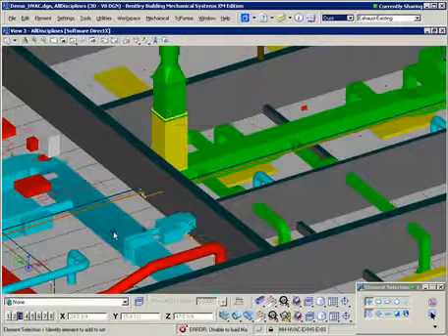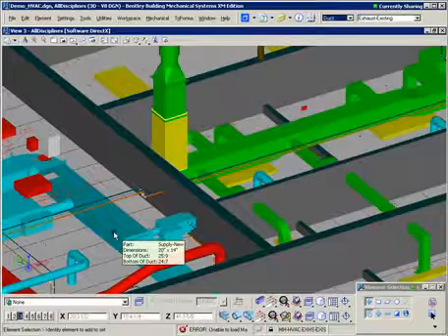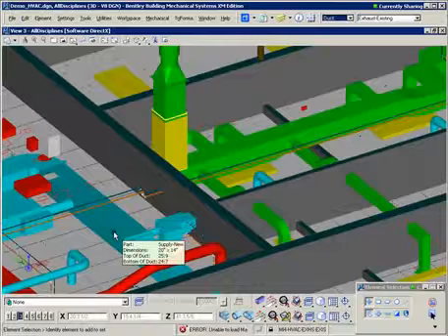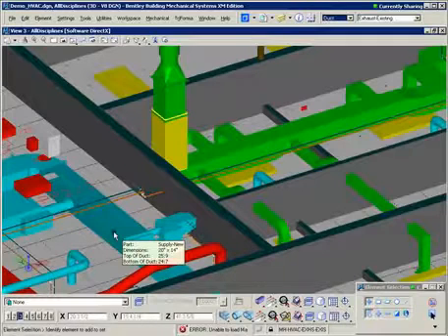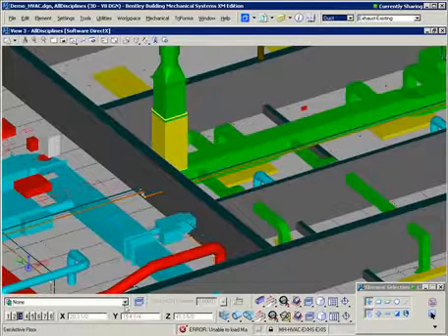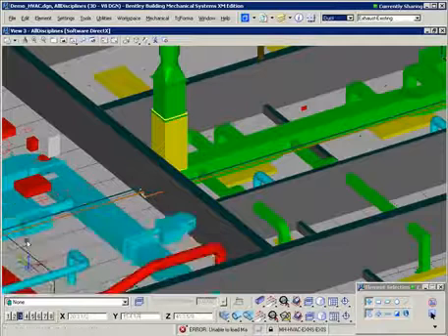So if I go to different types of elements, like the ductwork, you can see different things. For example, the top of the duct and the bottom of the duct in relation to the floor you're in, meaning this floor manager here tells at the moment we have no floor activated, so let's go and activate the second floor.